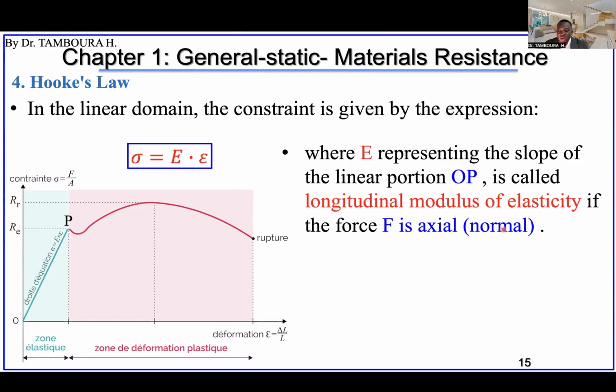I think you understand. So the E here is also what we call Young's modulus. The Young's modulus is just this one. So Young's modulus is nothing but the coefficient of proportionality between stress and strain in the linear zone. Please remember, in this zone, not here. If you enter this zone, we are not working in this zone. This green zone, not the red one. Okay, Young's modulus.